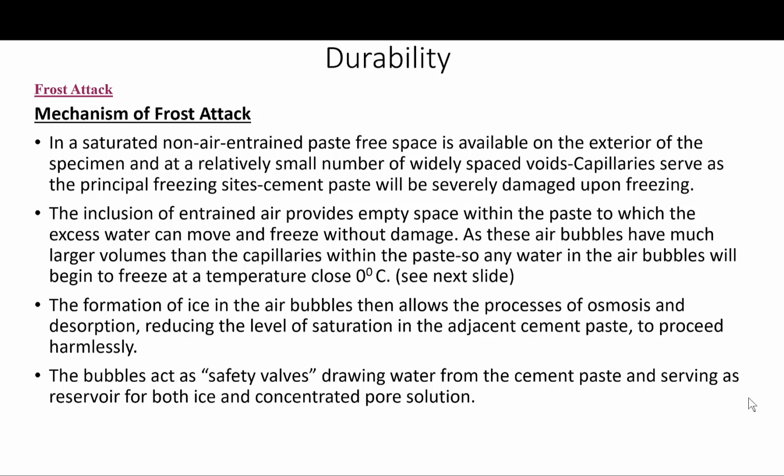The air bubbles have much larger volumes, as we have explained before, than the capillaries within the cement paste, and therefore any water in the air bubbles will begin to freeze at a temperature close to zero. The air bubbles are mostly empty, but may have a film of solution on their surfaces that is thick enough to freeze. So the formation of ice in the air bubbles allows the processes of osmosis and desorption, which I just explained, reducing the level of saturation in the adjacent cement paste, to proceed harmlessly.